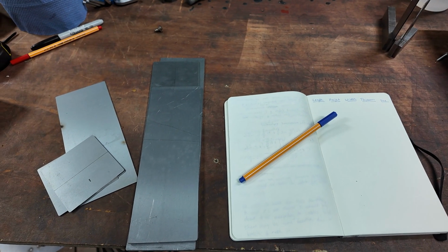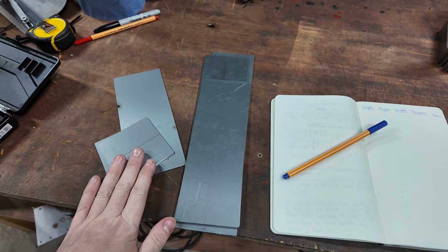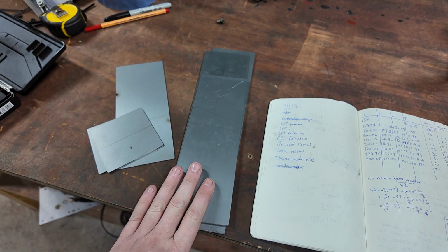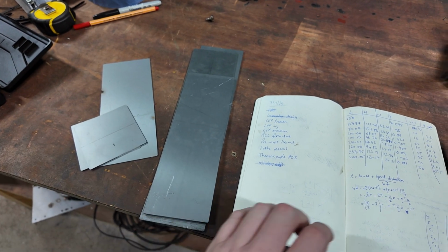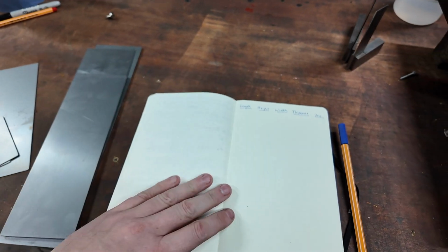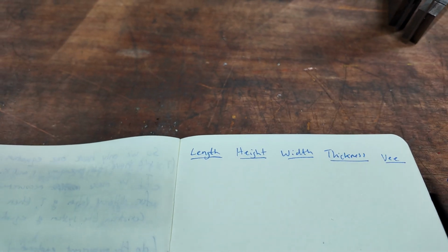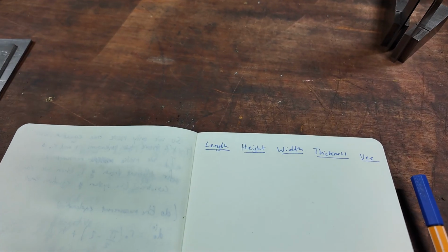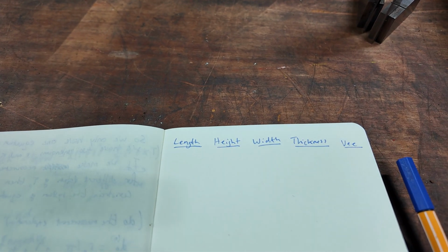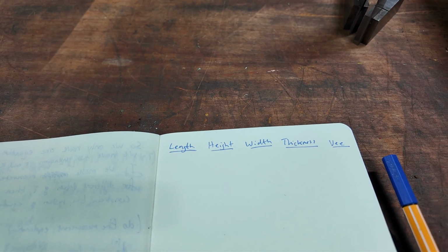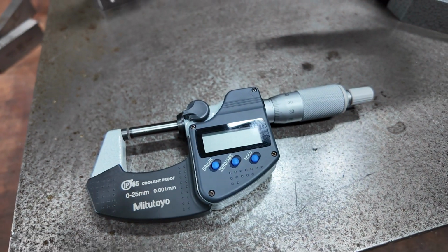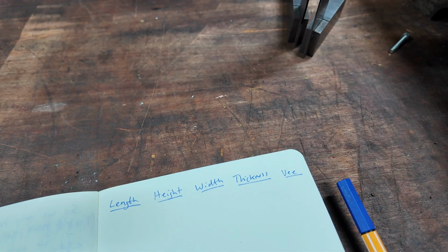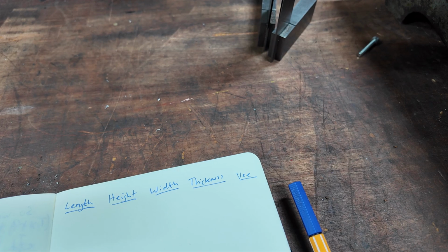Right, so as discussed upstairs, we're going to come and do some measurements. I've got lots of pieces of 1mm steel blank and lots of pieces of 2mm steel blank, all cut at different lengths from the laser cutter. We're going to fill out this table. We'll measure the total length of the flat piece on the vernier, or the height gauge. Then we bend it, and it doesn't matter where we bend it, we measure the height and the width, and then we measure the thickness using the fancy calipers, micrometer, and we're going to do lots of bends with lots of different V's.